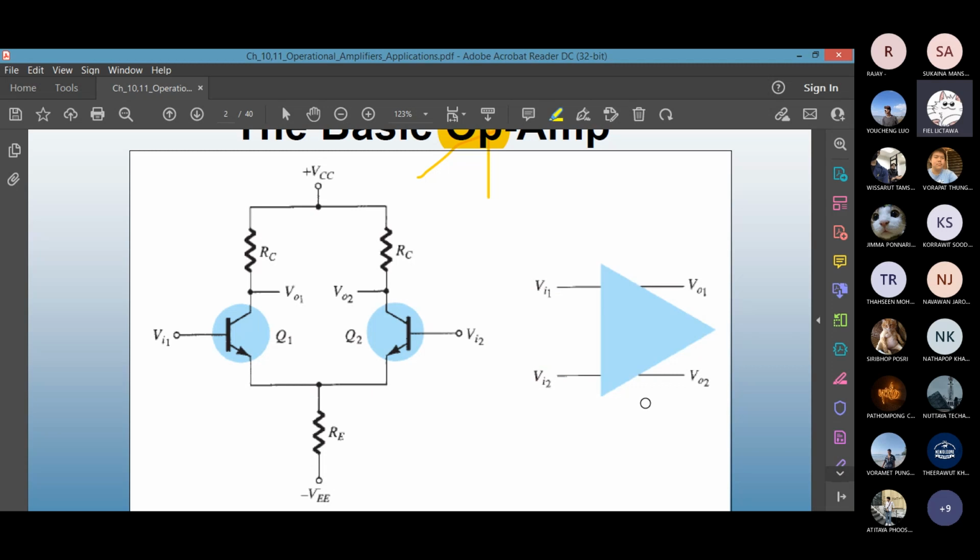The second mode of input, both inputs will have some applied signal but in 2 opposite polarities. This is called the double-ended or differential input. So I put an input right here for input signal 1. The other one will be opposite polarity. This one is a double-ended input.